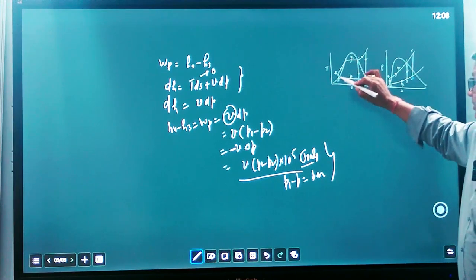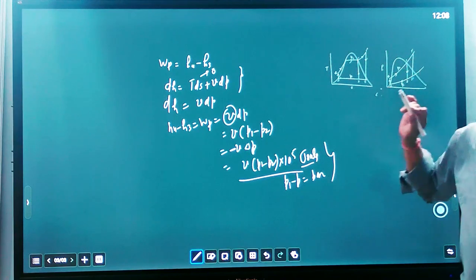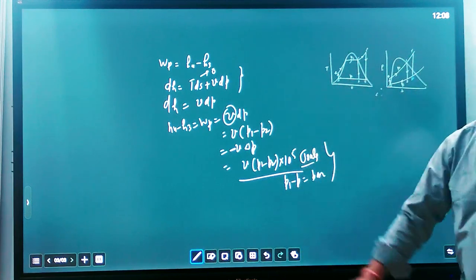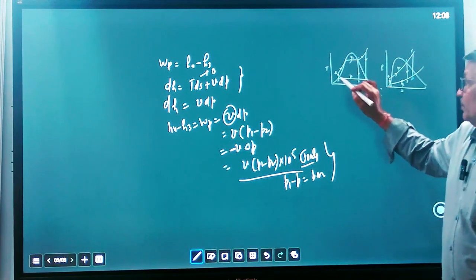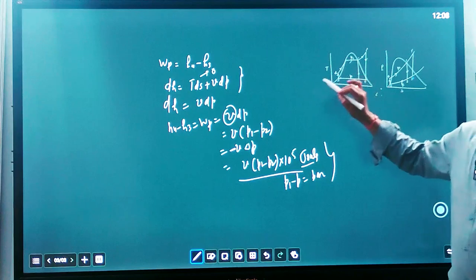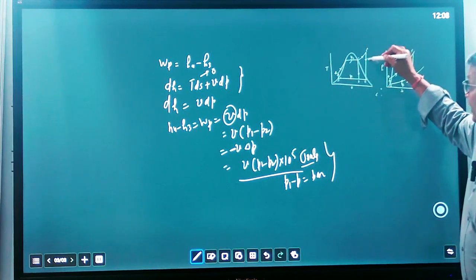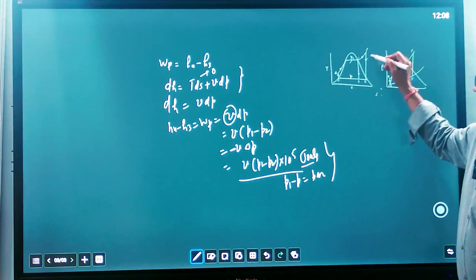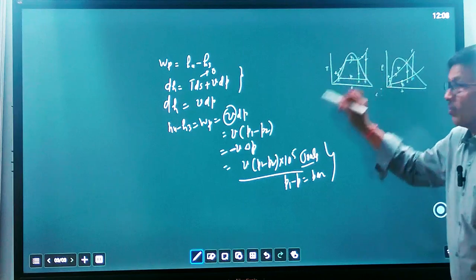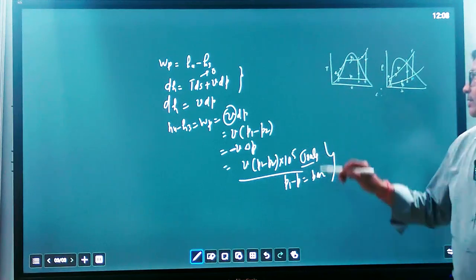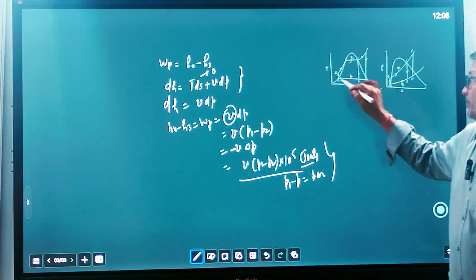If the fluid is in gaseous state, and process 3-4 is handled by the pump in gaseous state, then the work that we get during expansion in the turbine will be less than the work required to pump back the same gaseous fluid from 3 to 4.